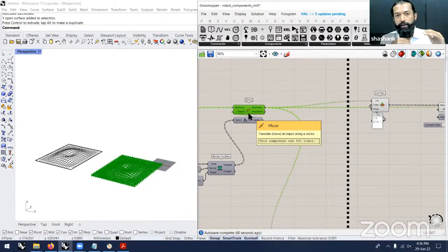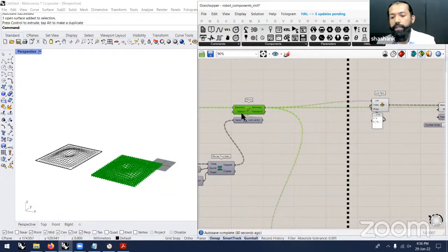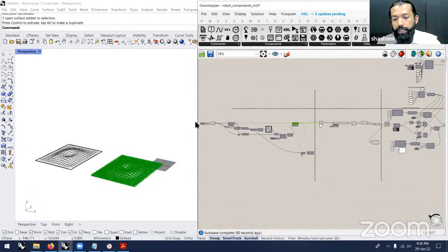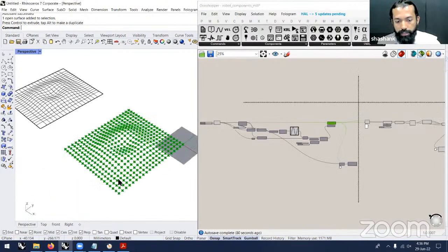And the second component is after you finish the roughing, you start off with a finer tooltip and you go over the parts a couple of times to get the final finish. So that smoothing is what we'll be looking at currently. One of the things that you need to understand is what drill bit you have. Based on the drill bit, you're going to divide your surface into points or lines, and make sure that you have some bit of overlap, because that overlap is essential to ensure that no material is left over. Otherwise, you're just going to create streaks of remainder material, and that's not something that we want.